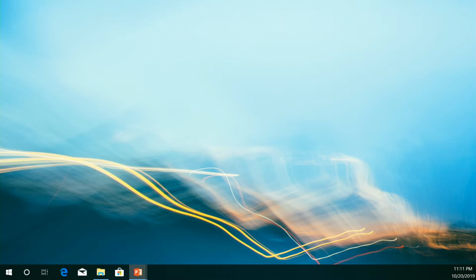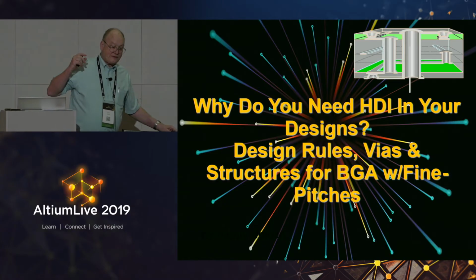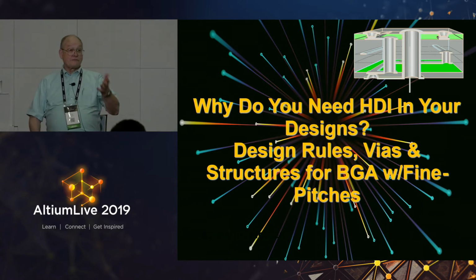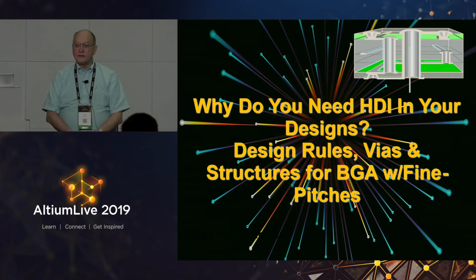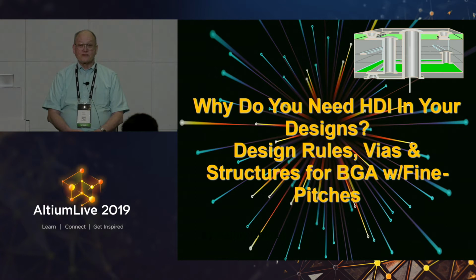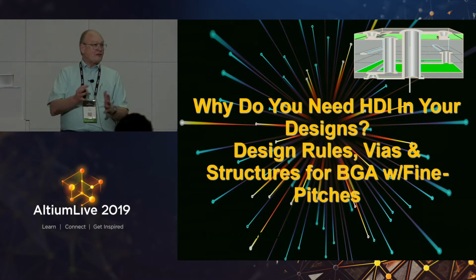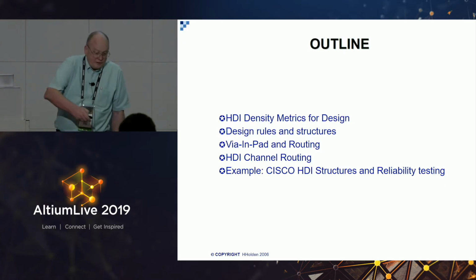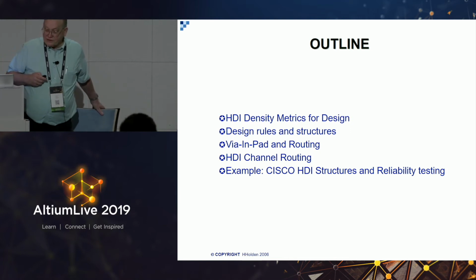next section. So for many of you, you've already gone past this decision. Do you need it? A lot of people don't have to use it just yet and may never have to use the high-density interconnect. If the pitches aren't shrinking and you can get 1.27 millimeter devices on ball grid arrays, if you don't have signal integrity or other issues like that, you have plenty of room and don't need to worry about shrinking the size. But for the rest of you,